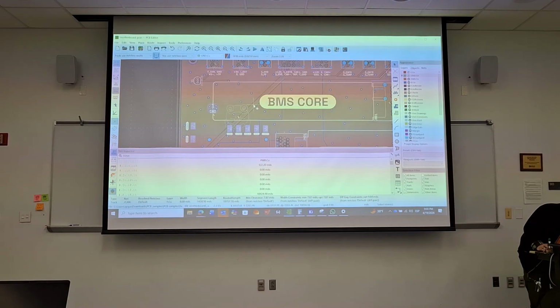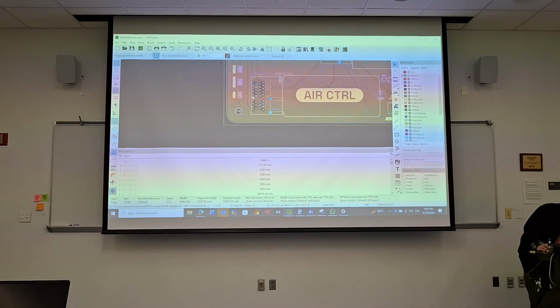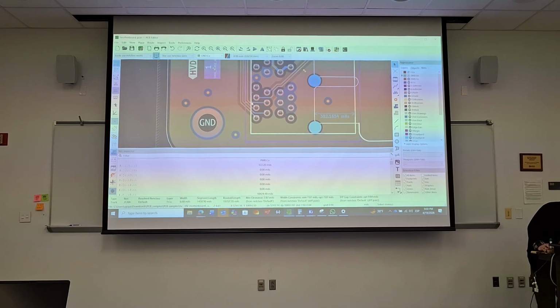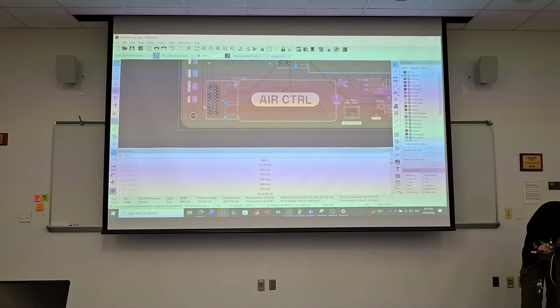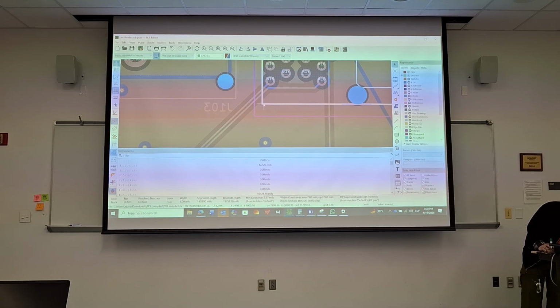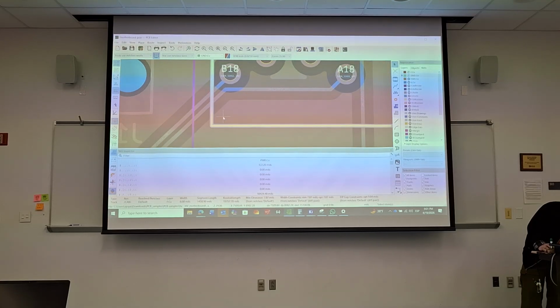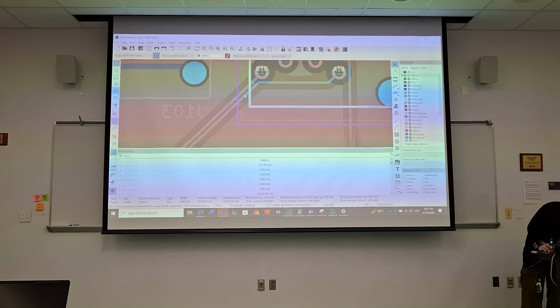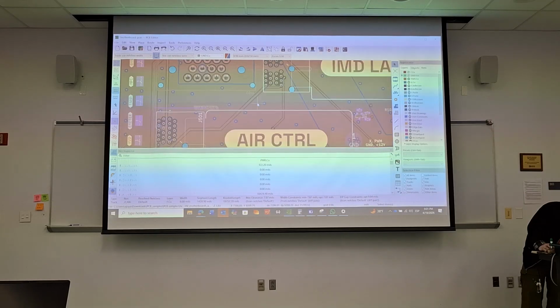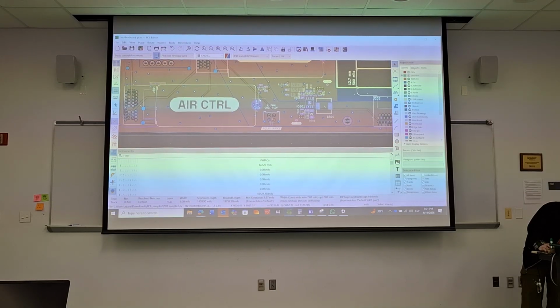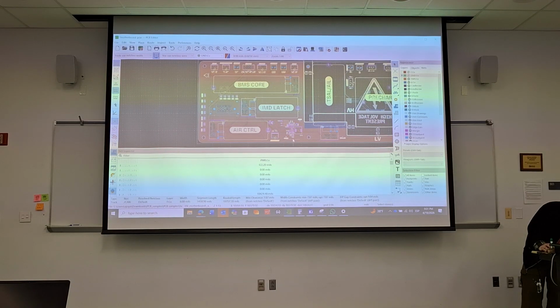These do not need to be that close. So yeah, there are some things that are definitely not helping this. Like, this has no reason to be routed like that. And again, since all of this is referencing power, if there were short traces, not a problem.